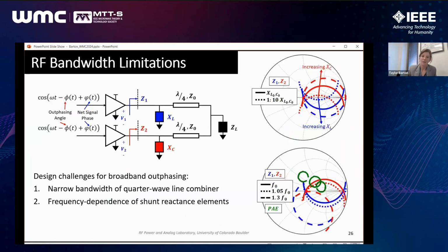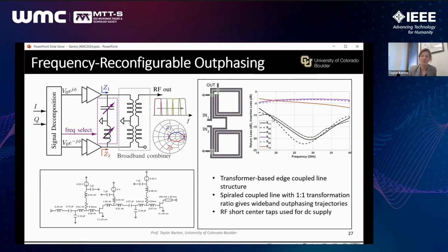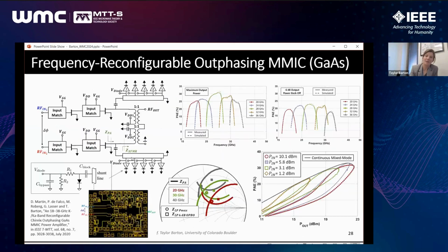modulation. Bandwidth is, of course, a major consideration, and we'll wrap up here, but essentially, I mentioned that we could do transformer-coupled structures if you go up high enough in frequency. So we have a PA that used a transformer with shunt reactive elements, and the reactive elements are implemented with transmission lines with pin diodes that let us select the effective length of the line by grounding at different points. And this allowed us to track that RP CP model, that parallel RC, in frequency, and get the load variation.